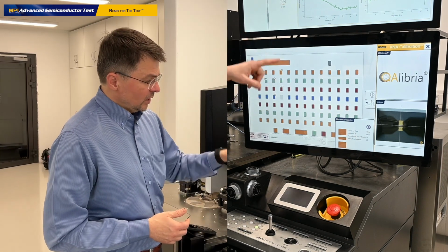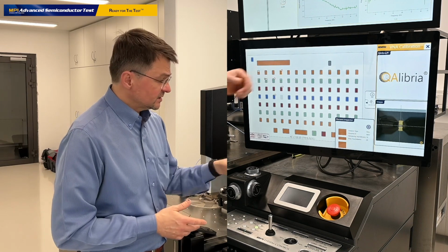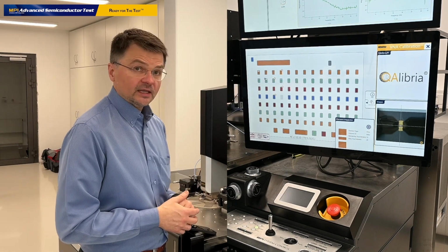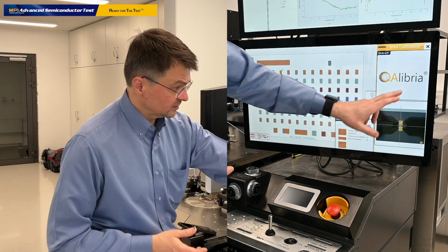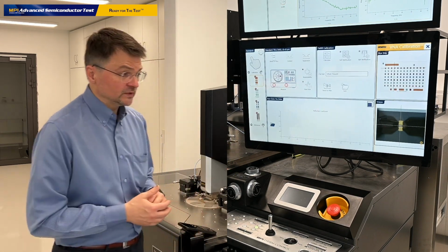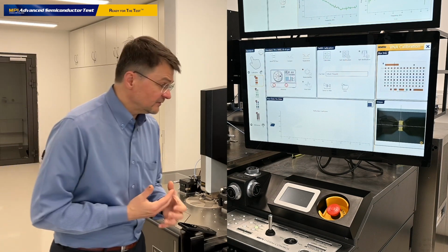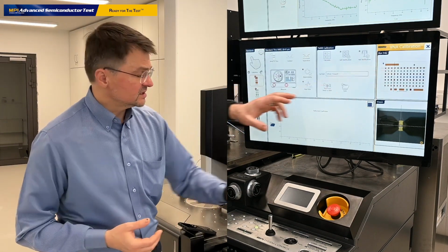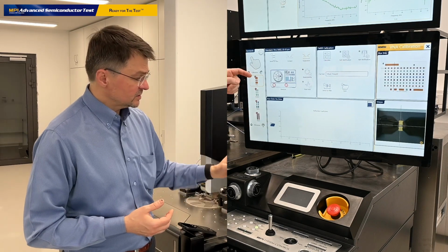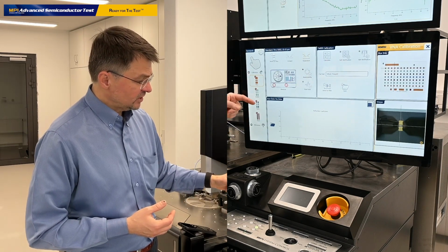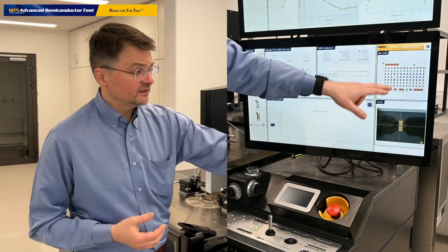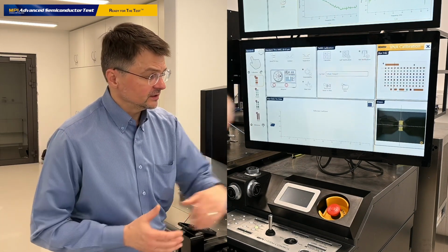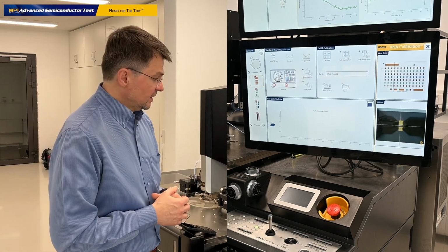And well, now we have a list of the selected standards that will be used for the calibration process: through, load, short, and the open standard. And we have everything defined that we want to be defined for the calibration process. Based on the list of the selected standards, they're all displayed here. So we will be measuring through, match, open, and the short, and these will be the standards which we currently selected, and we can monitor it during the execution process.